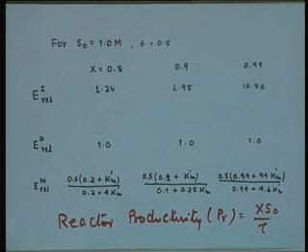in the case of PFR than CSTR. The quantity of enzyme required, or the value of tau, increases more in the case of CSTR with increasing fractional conversion, but the productivity increases more drastically, very significantly, in the case of PFR when fractional conversion is increased.